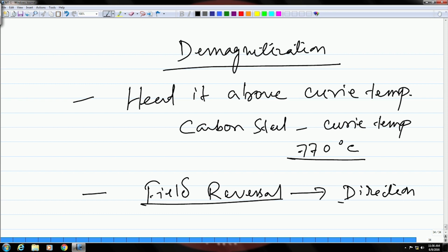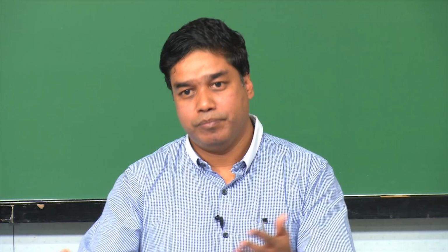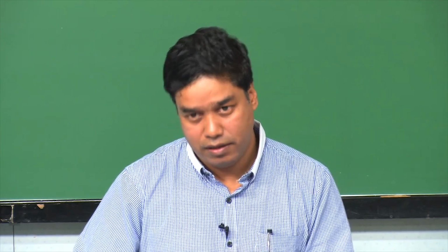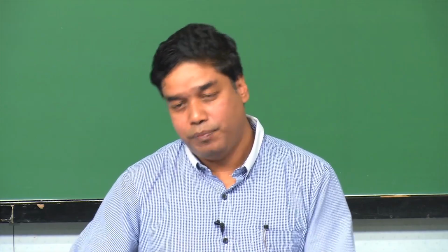So, this is another advantage if you know the direction of the magnetic field. Okay. The other advantages we have already seen, like the orientation of the defects with respect to the direction of the field, the visibility of a defect would depend on that. Okay.